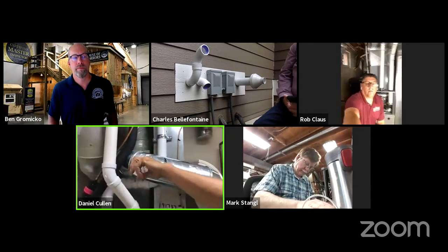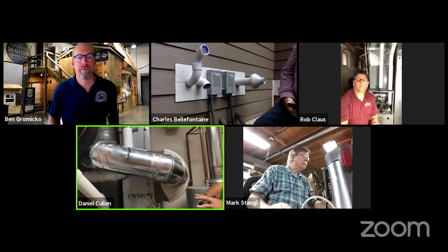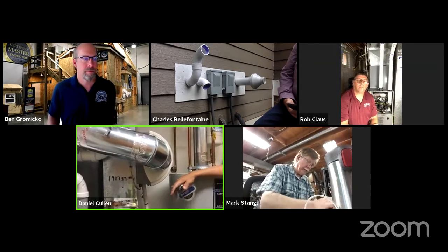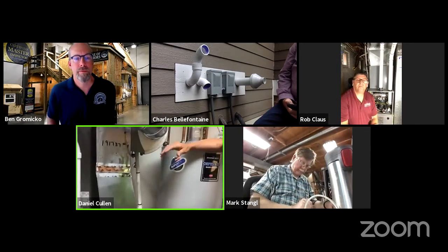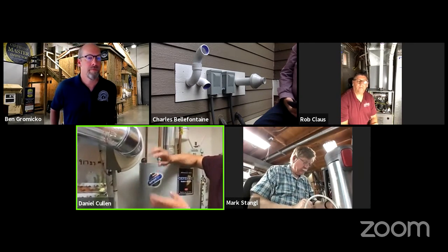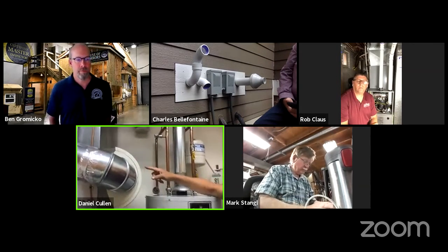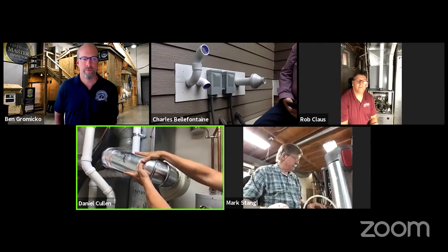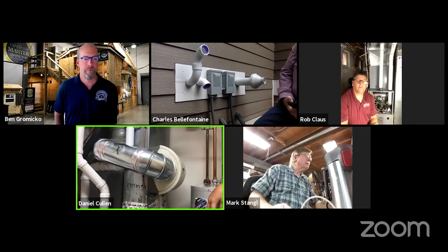Now, this one is a bypass humidifier, as we all know, that works on a pressure differential between the supply and the return side, pushing the moisture across the humidifier element. In a house like this, where we have 2 levels and only 1 unit and not really great return air setup, this ideally would be the type of humidifier with the little electric fan here that doesn't steal air from the supply in order to push that moisture into the airstream.